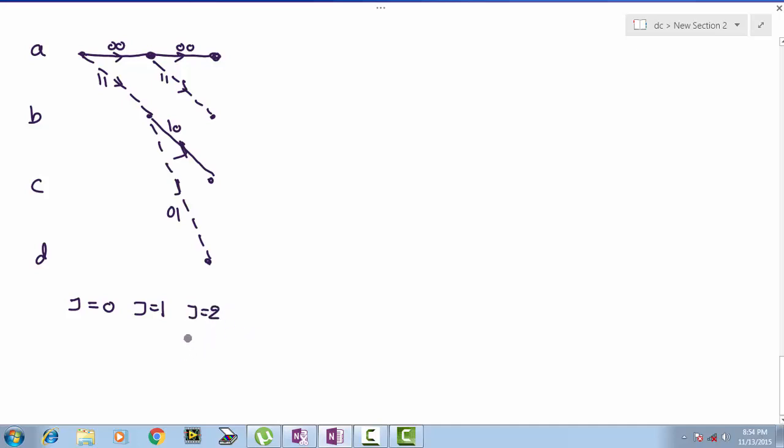Now see, for our convolution encoder, constraint length K is equal to 3 and capital K minus 1 is equal to 2. So j equal to 2. The first K minus 1 levels are for departure of the initial state. So we completely departed from the initial state, and now at level j equal to 2, we have reached all the states. And what we said earlier, from K minus 1 to L, the structure is periodic.